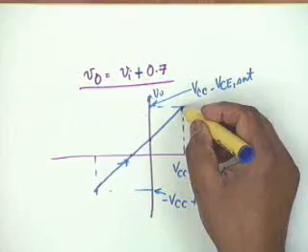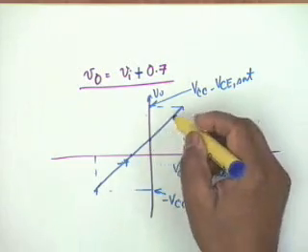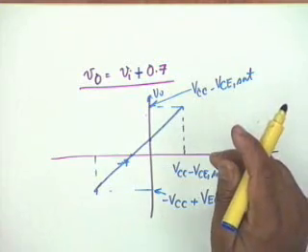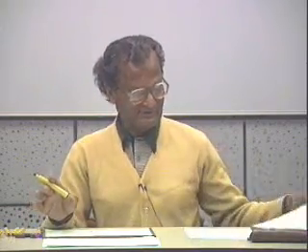So we won't go up to this limit anyway. If we are somewhere in between, then there is no problem. Okay, we should not go to saturation. What we should do is to see in the CRO that the output waveform is approximately the same as the input waveform. That is, there is no crossover distortion.